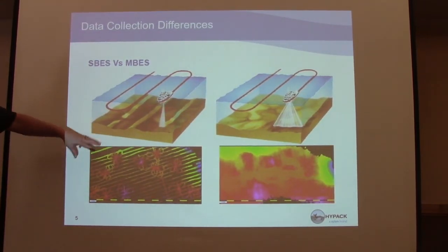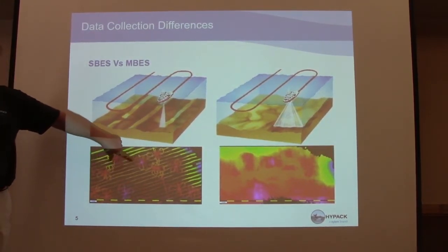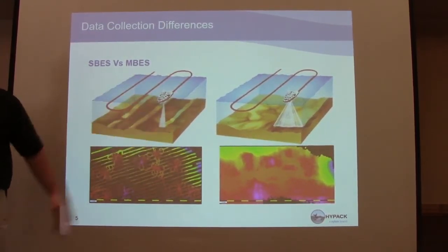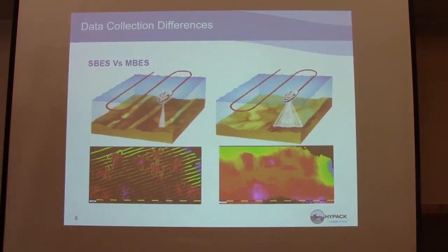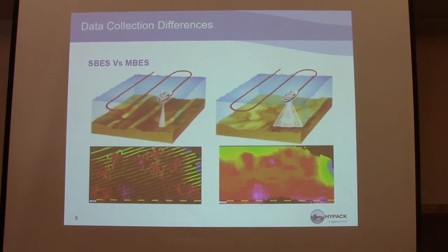If you make a matrix around your survey area, you can use the sonar for matrix updates. With multi-beam, you're painting the matrix full swath. You don't have to display the full swath updating the matrix. I recommend when you're doing HYSWEEP surveying, just to make sure that when you're done surveying, you have good overlap.